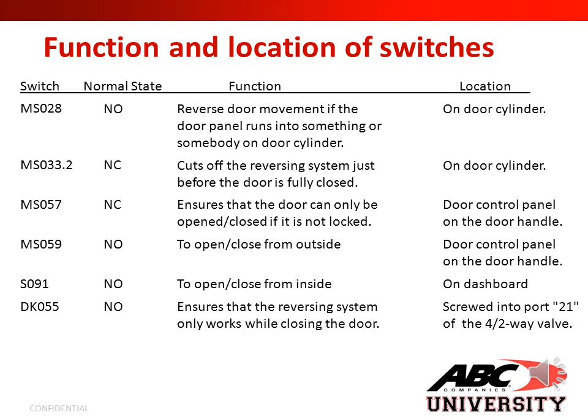Functions and locations of switches. MS028, a normally open switch, reverses door movement if the door panel runs into something or somebody on the door cylinder. Location: on door cylinder.